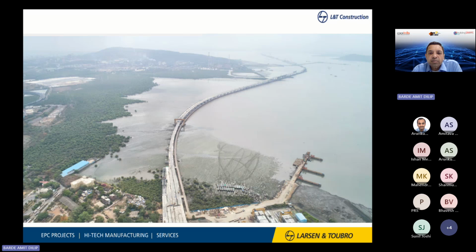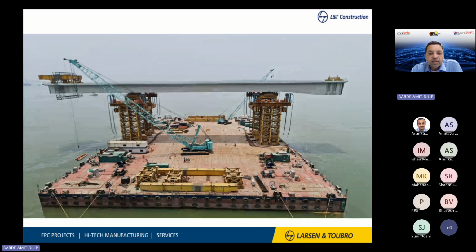I think it's precast plus there are some segments which are steel, right? So that's where that technology is coming, where we are building the speed. And if I have to give you a scale on that speed, what you see is a steel girder. We call it OSD, which is orthotropic steel deck. Because of that span, it's about 150-meter long, about 12-meter wide, and weighs about 2,500 tons.